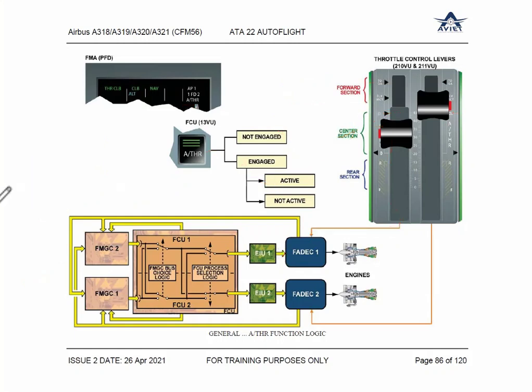So what does the pilot have to do? He will get the message here, TOGA LK, TOGA lock. So the pilot has to disconnect this. Click, disconnect the auto thrust, and then FMGC, or sorry, FADEC, will play the role to bring the thrust slowly to the lever position. Otherwise, there is a big jump.